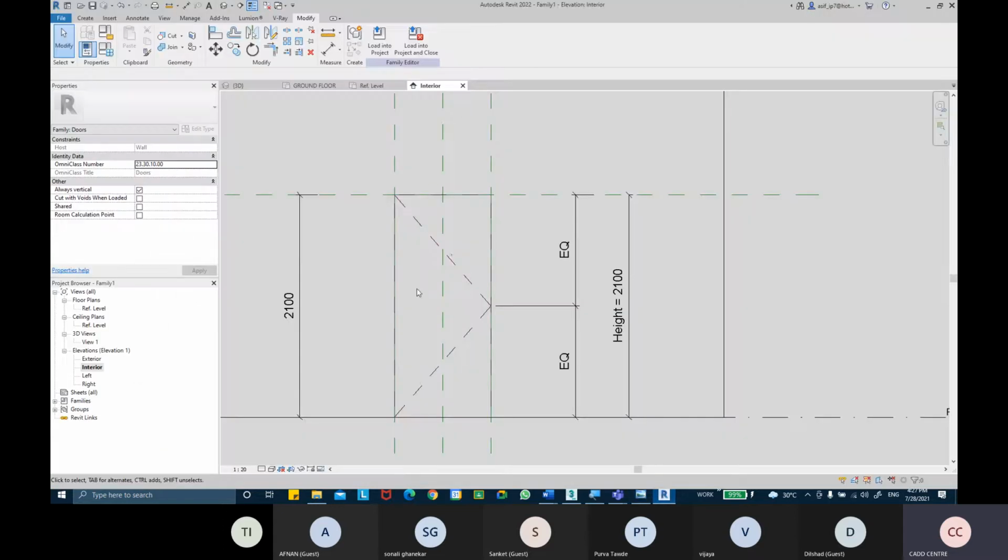So I need to create over here. Now this door jam would be on three sides of the door. So it will be on the left panel, on the top panel or plane, and on the right plane basically. So it will be on three edges actually, the left edge, the top edge, and the right edge. Okay. Right, so let's create that specific door jam first today with parameters.